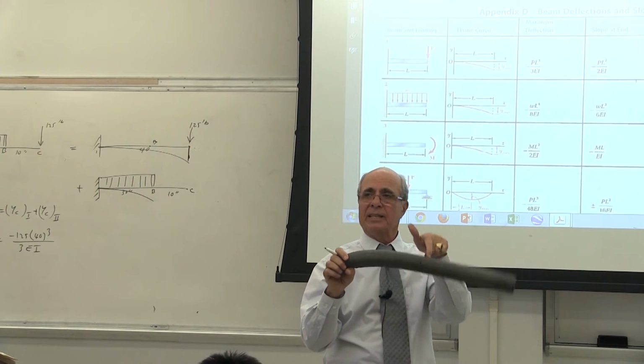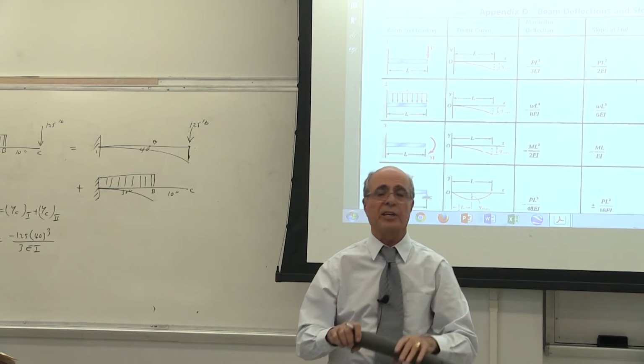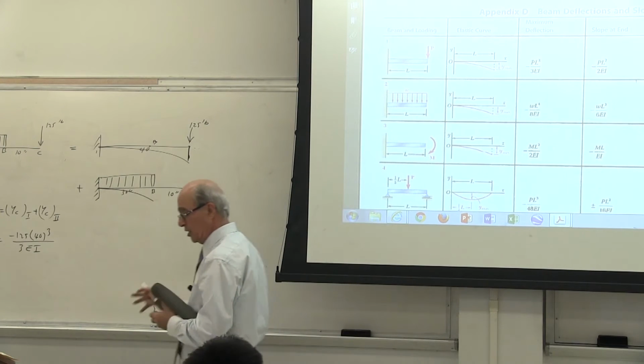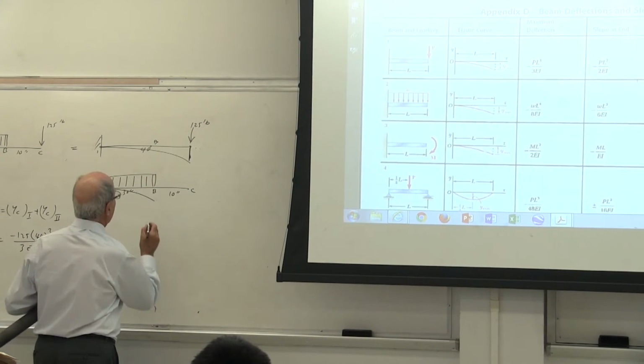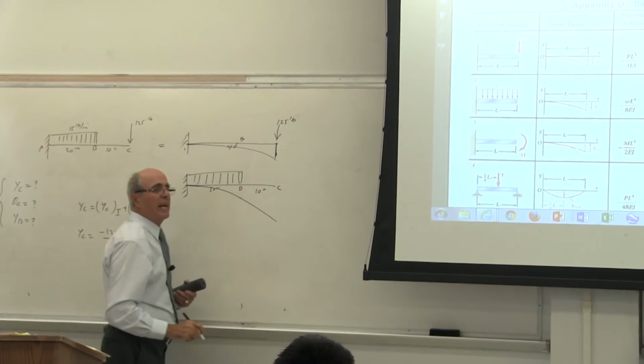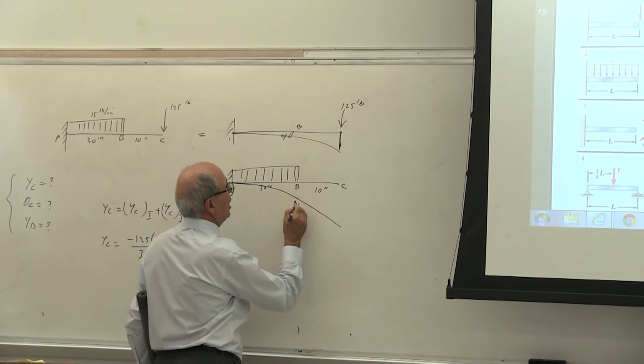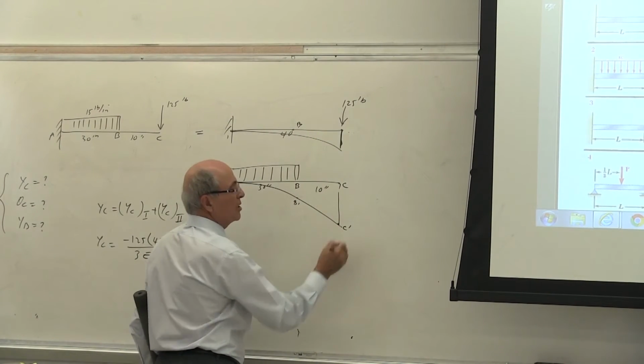The rest of it is a straight line, but it is tangent to this curve. Is that correct or not? You want to put this in your notes. So this one becomes, in exaggeration of course, a line tangent to that. And you are not looking for this BB prime. You are looking for distance CC prime.